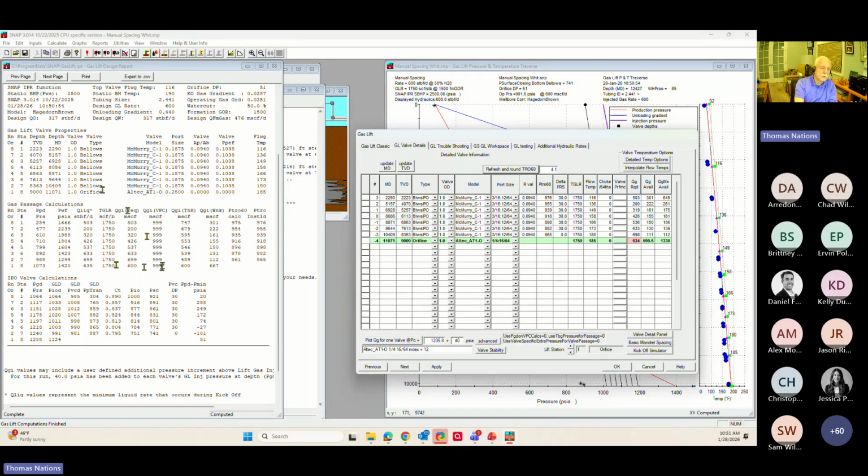So here are some of the detailed calculations of our gas lift installation. So here's all the details. Here's your production pressure at depth. Most of the acronyms are API gas lift recommended practice acronyms. So, for example, PPD, production pressure at depth. PWF, pressure well flowing. That's at a depth also. But typically, if it says an uppercase letter P, being a pressure, if it's got a D in the acronym, that means it's a downhole pressure. If there's no D, it's typically a surface pressure.